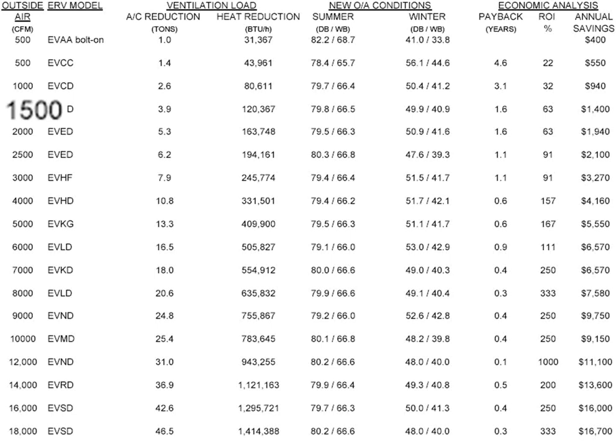So basically, if I take 1,500 CFM of ventilation air coming in, I'm able to downsize the rooftop by 4 tons. That means if you were going to buy a 15-ton rooftop, now you're going to buy an 11-ton. Right? If you can't buy an 11, you'll buy a 12.5 or whatever the size is. But you can buy one that's literally 4 tons smaller than you thought you needed.